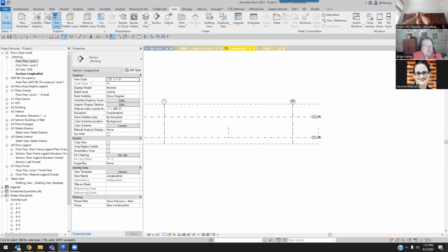So honest truth for me, and I work with several structural firms who get into this, we create an opening family that puts in structural studs and headers. So we've nested into an opening family the beam as well as the headers, et cetera. So when you put an opening in, you can actually, I believe it's a door for the one structural engineer I did it for. That way, if you wanted to, you could copy monitor the architect's door and swap it out for your door. And then you can say, hey, in this case, this door is getting 2 king studs, 2 trimmer studs, and this size header, whatever.